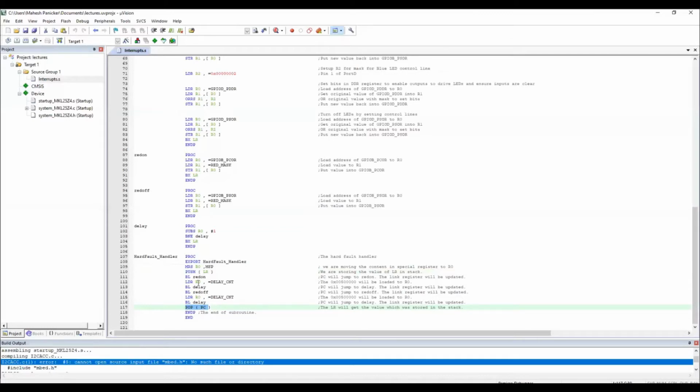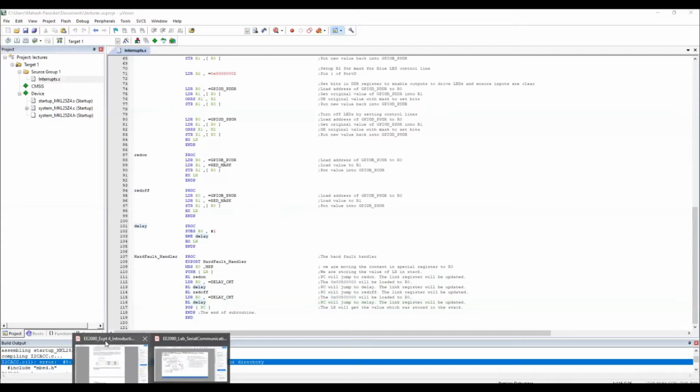So that's the objective. So inside here, what I'm actually doing is making on the red LED inside the board, then giving some delay, of course, and then making the red LED off. That's what I'm doing. So red LED on, then delay, red LED off, then again delay, then it goes back to the main program. And then how to configure the red LED. So that's the critical aspect. So you have to go back and see the manual.